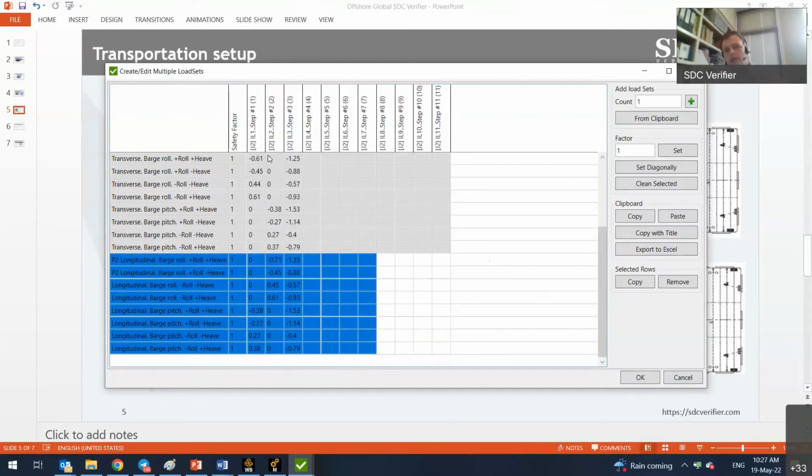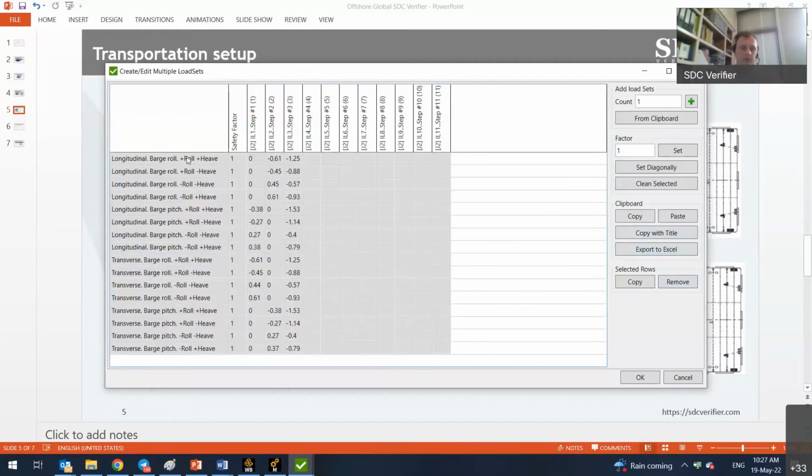You can apply every load, every influence as a separate load, but that obviously influences your calculation time and the amount of loads you have to apply. So this trick is much more convenient, because you just apply 3 accelerations with unit loads, and then with factors you do the combinations that you need.